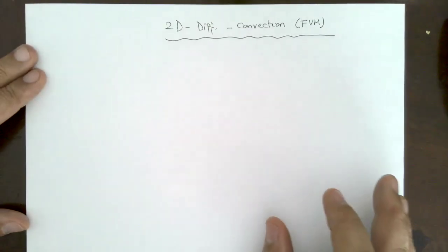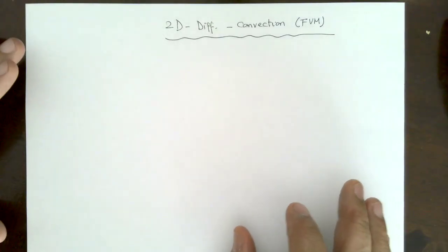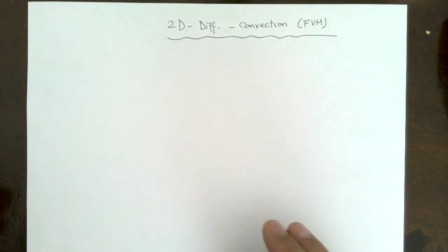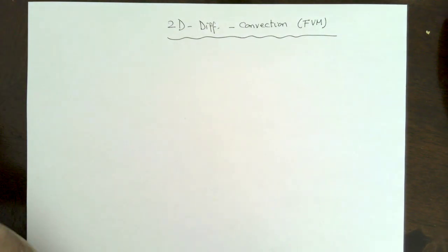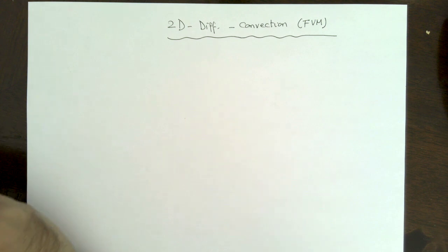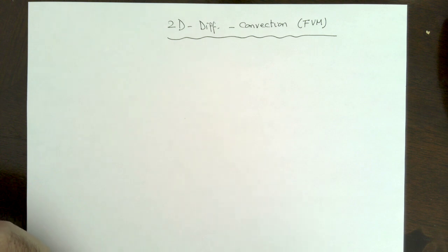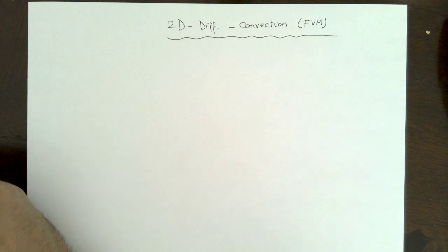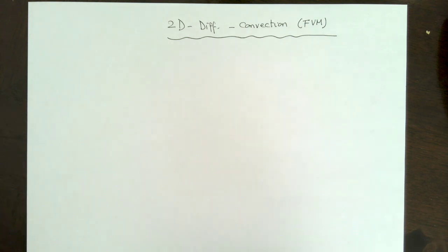So we will take the level of complexity and hardness for the diffusion convection problem from 1 dimension into 2 dimensions. It's not really complicating the issue. It just requires additional steps, because moving from 1 dimension to 2 dimensions is going to add more cells around the central point. So instead of only dealing with east and west nodes, we will have the north and south nodes. And we dealt with that before when we covered the 2-dimension diffusion problems, but now we are looking into the